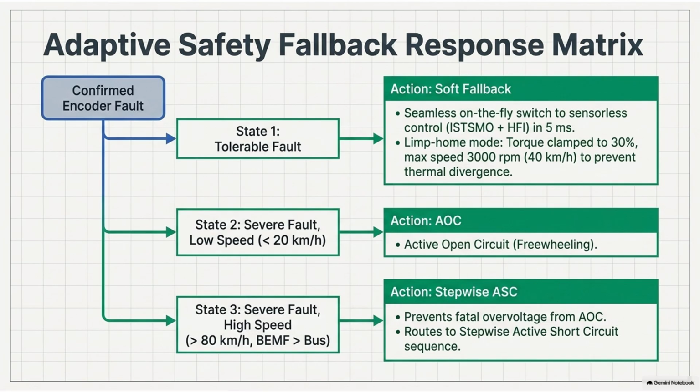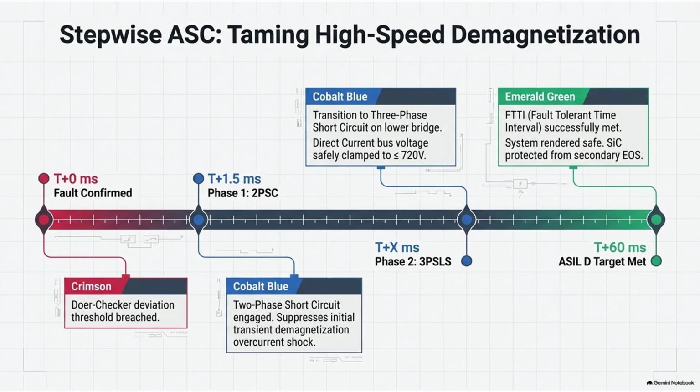Here's where it gets really interesting, though. The third design mandate deals with something that sounds like it belongs in aerospace engineering, not automotive. Oh, you mean the cosmic rays. Yes. Hardware ECC and BGCRC to protect against single-event upsets caused by cosmic rays. Wait, you're telling me outer space radiation can actually cause a motor to stall out on the freeway if we don't put ECC memory inside the car? I am. High-energy neutrons generated by cosmic rays striking the atmosphere are constantly passing through the Earth and through everything on it. Including cars.